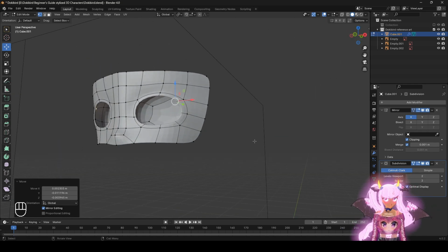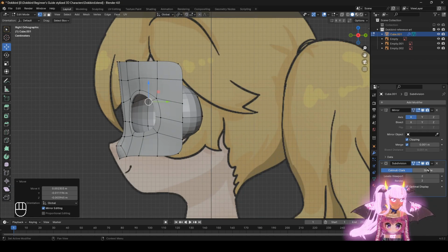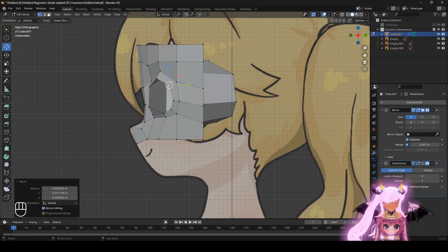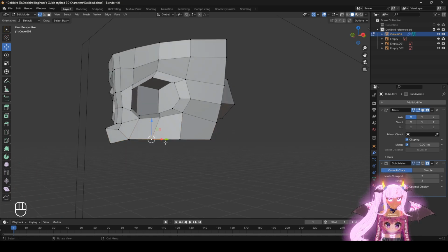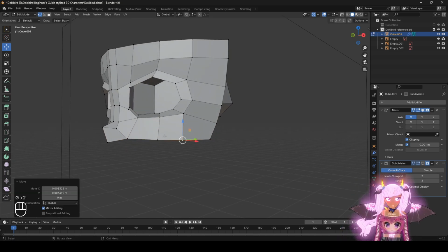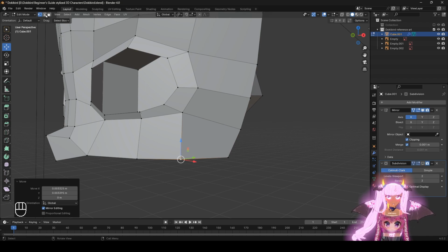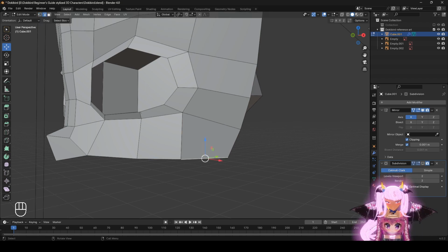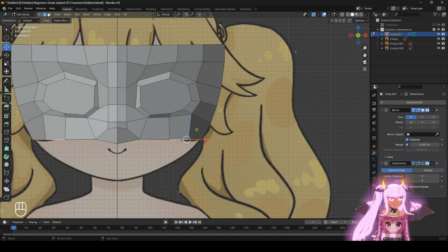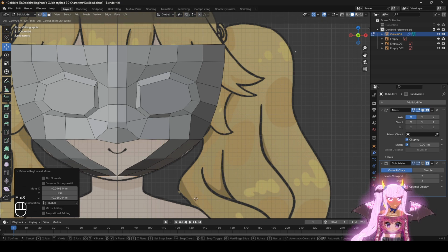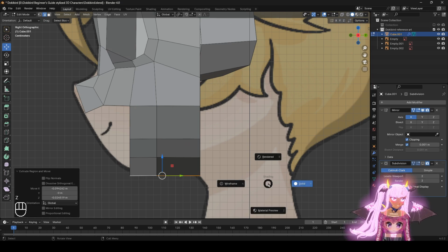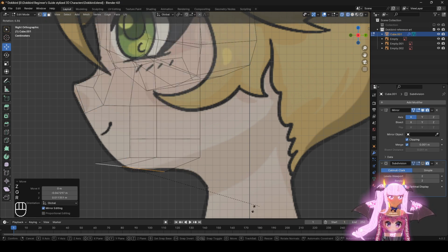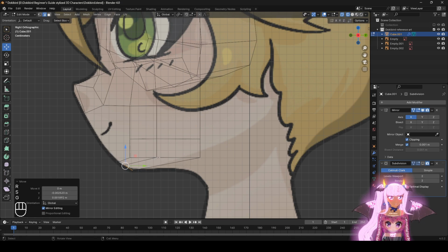It's not done yet. Now it's time for the bottom part. Alt left click right here. We could scatter it out right here. Okay, we're going to do these two. I'm going to do edge select, click this, hold down shift and left click this. Now we're going to go E, E, then E, all the way right here. Look from the side view and we're going to start to fix it. Just Z, left click over here, and S. We're going to start making a mask.